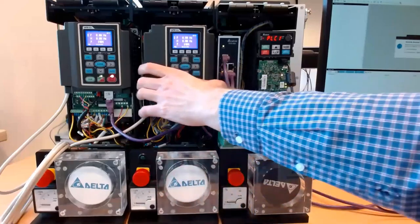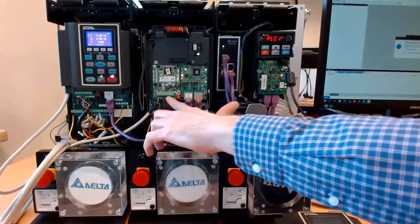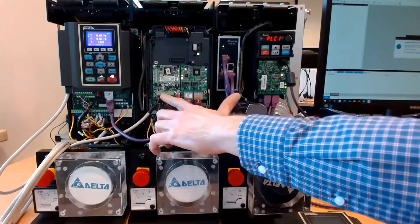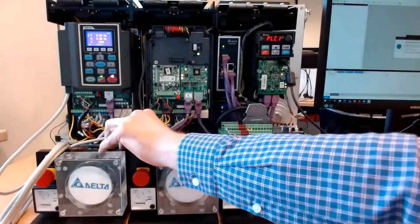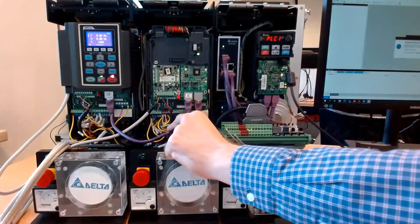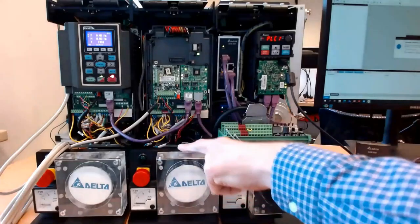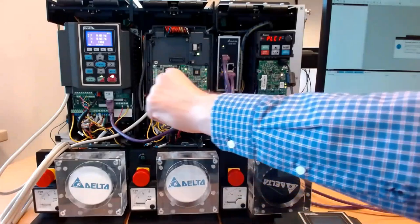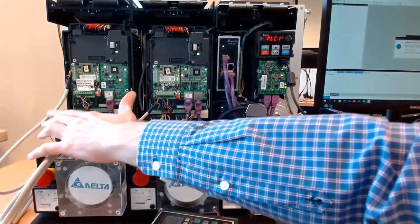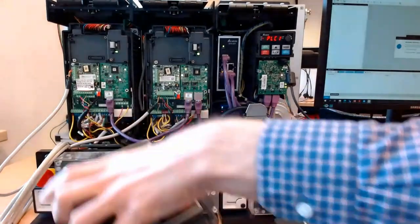Now, all PG cards have different terminals. So you have firstly PG1 for connecting the motor. You have PG2 for connecting an external source of pulses. And then you have PG out, where you can get pulses out to another drive. So if this drive were configured as a master, then you could take the pulses which are coming in from this motor and you could output them on these terminals. And you also can see here, in this configuration, I have this drive running as a master, and this drive is configured as a follower.